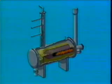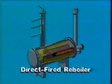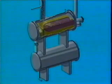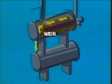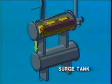Reboilers can be direct-fired or heated by steam or hot oil. The direct-fired type, containing a removable firebox and fire tube, is normally used. An overflow weir maintains the glycol level in the reboiler. Excess glycol spills over the weir and flows downward into the surge tank by gravity. When the glycol level is low in the surge tank, fresh glycol is added to the reboiler, so it can be dried before going into the surge tank.